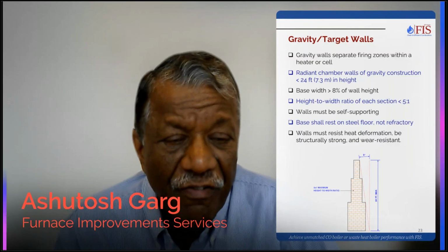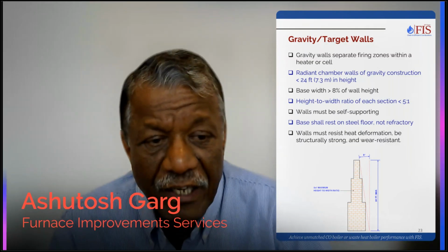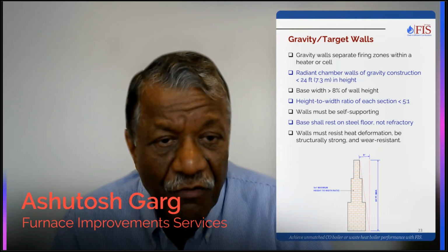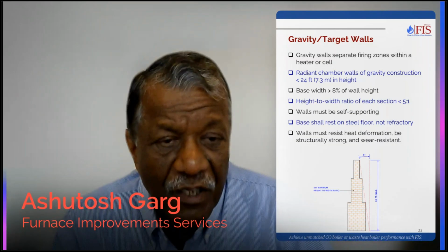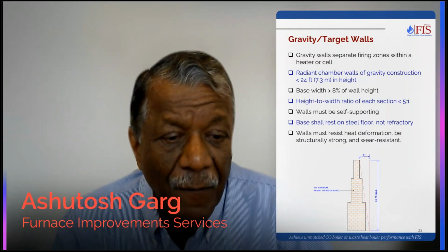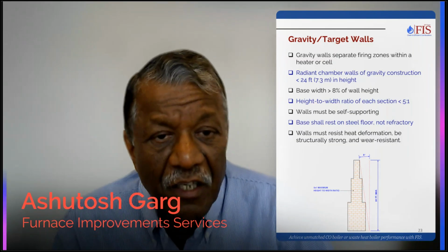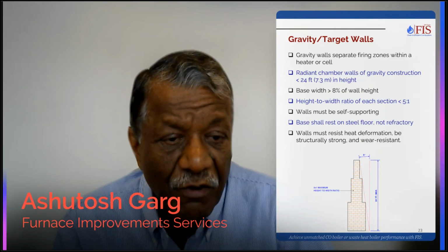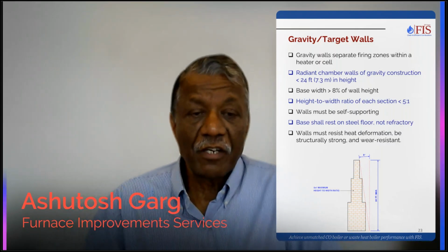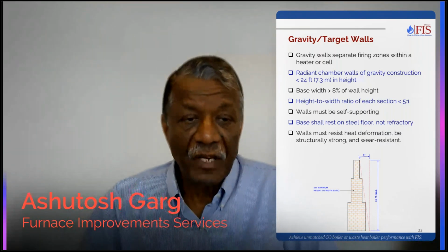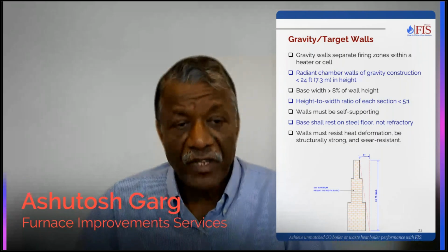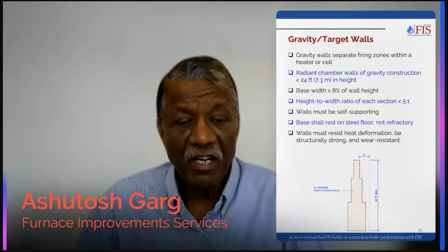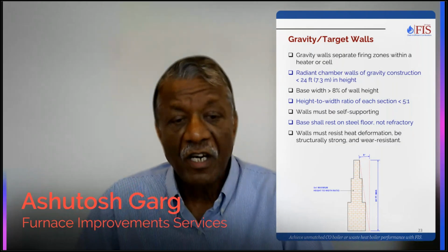and they have a lot of weight actually, because we want to make sure that the base is stable. So the maximum height is about 25 feet, 24 feet, and the base has to be 8% minimum of the height. So it becomes pretty much 1 by 12. So about 2.5 feet of base will be required for a 24 feet tall brick wall. Yeah, so they are long lasting. Most of the time, if they are constructed properly, they would be long lasting, but sometimes they do crumble.